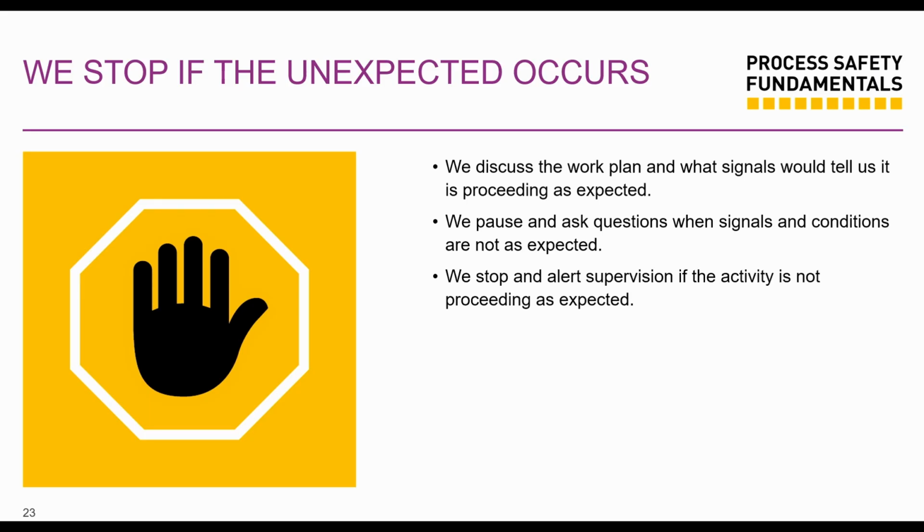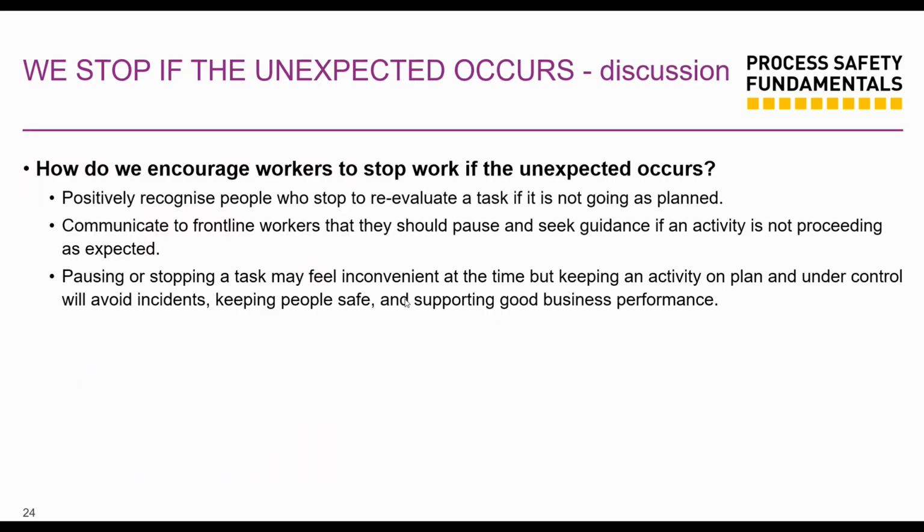Or you're operating a pump and you hear a knocking noise. Probably the pump is cavitating or has mechanical misalignment, and you just continue doing what you're doing, and the pump actually fails, and you release a flammable liquid everywhere. You should have caught this. You should stop if this is happening around where you're working. So stop if the unexpected occurs.